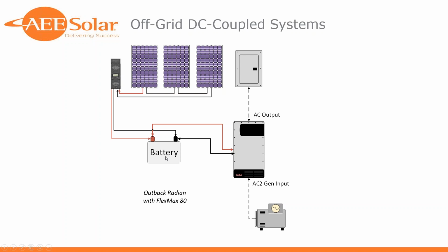And I say appropriate amount of power because it's going to raise or lower the voltage that the array sees based on what's being called for from the battery. As the battery, quote unquote, fills up, the terminal voltage is going to rise, and the array is going to see less potential to push power out. As the battery voltage drops, the MPPT charge controller is going to lower that voltage, create more of a potential, and try to harvest more out of that array.